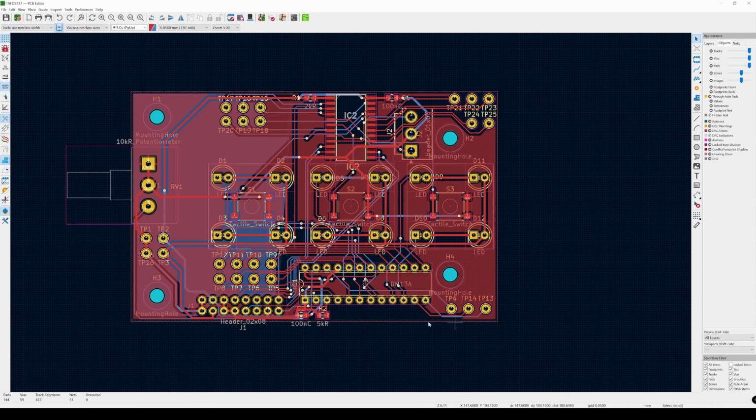Just add the zone around your whole PCB, make it a ground, and then to generate it, you actually need to click B, and B, like Bravo, updates the ground pour, and if you made some changes, you would need to regenerate it by clicking B each time. You can also do a similar pour on the backside, and that would look like this on the blue.